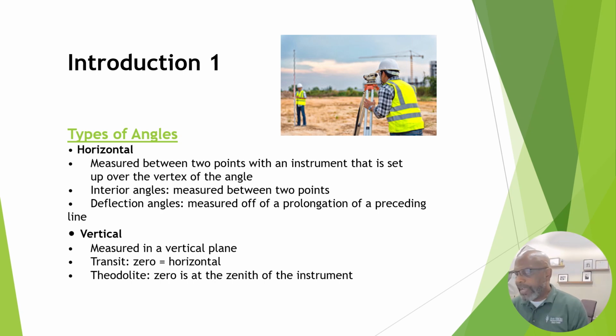So this type of angle is typically very small and requires great care because of the tendency to extend lines well beyond the limits of the instrument, which will cause error in the measurements or the layout of the angle. Now, the next one is the vertical angle.